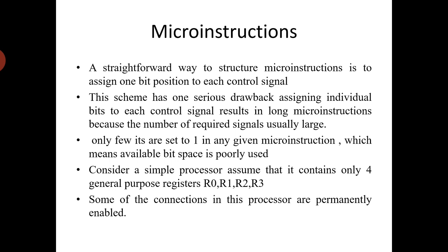However, this scheme has one serious drawback. Assigning individual bits to each control signal results in long microinstructions, because the number of required signals is usually large.